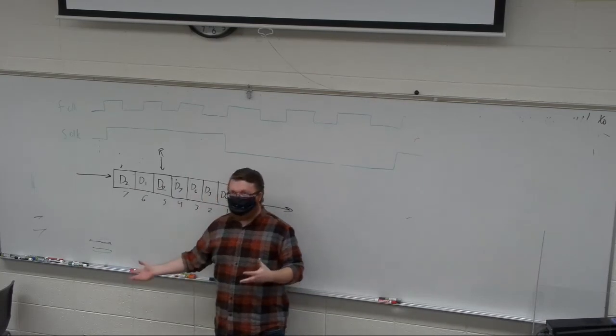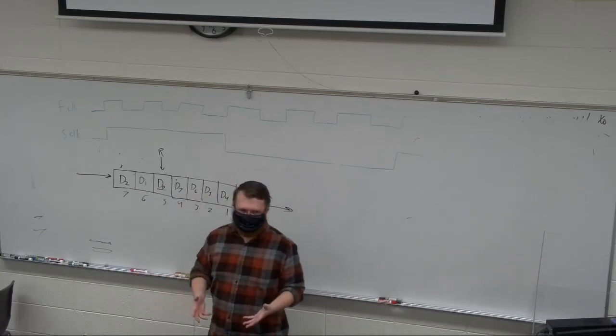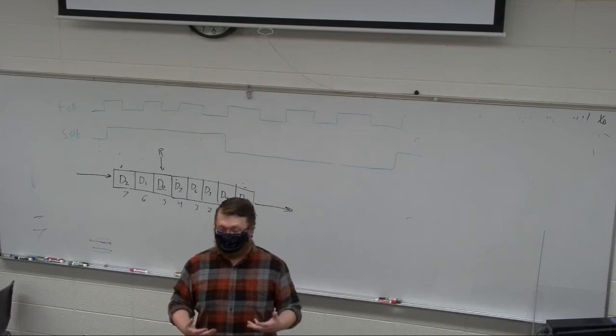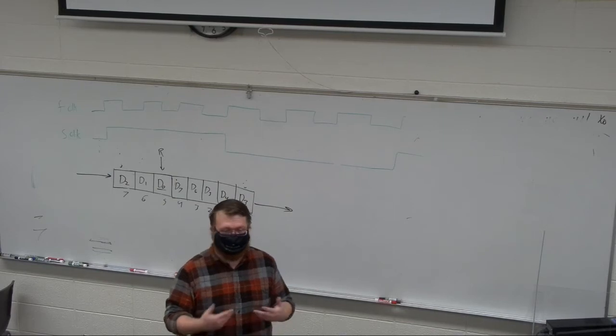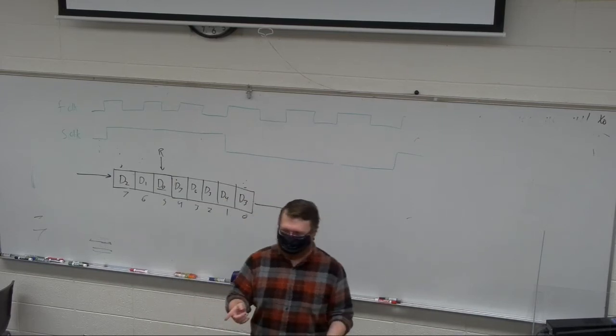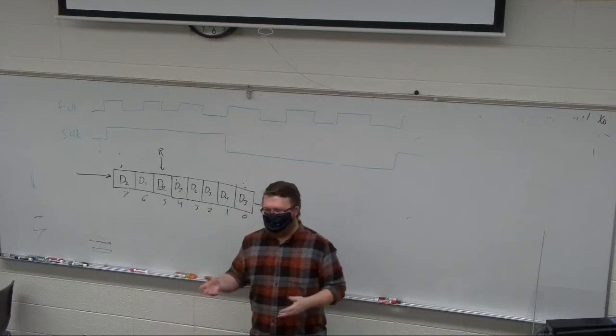Just using the IP core saves you a lot of work, because it will just work. You plug it in, hook up the wires like you're supposed to, just like we did with our memory, and now you have a first in, first out, which is what FIFO stands for, and everything works perfectly.